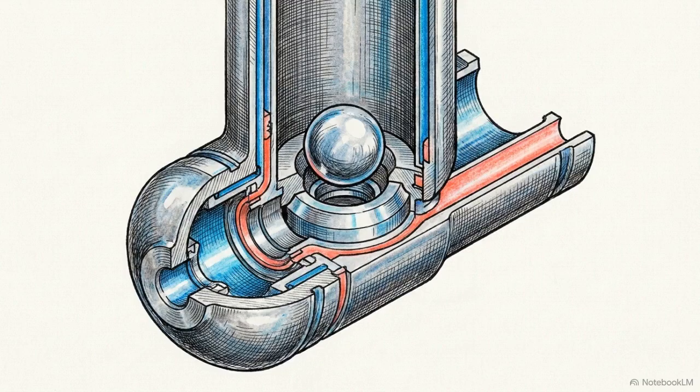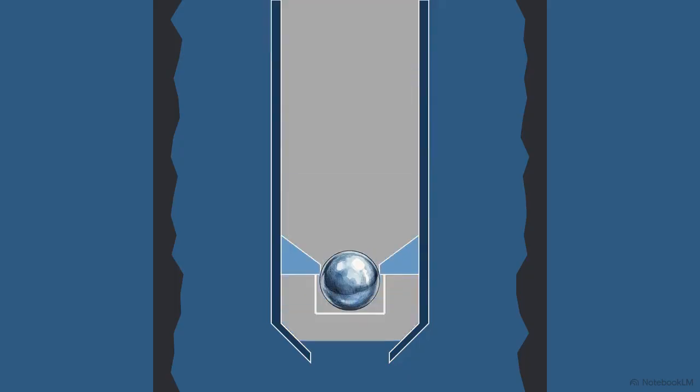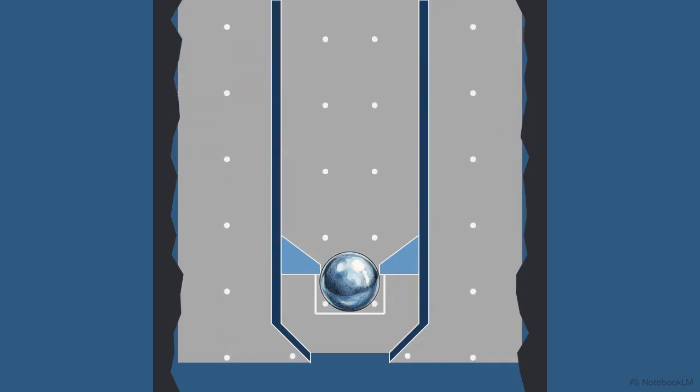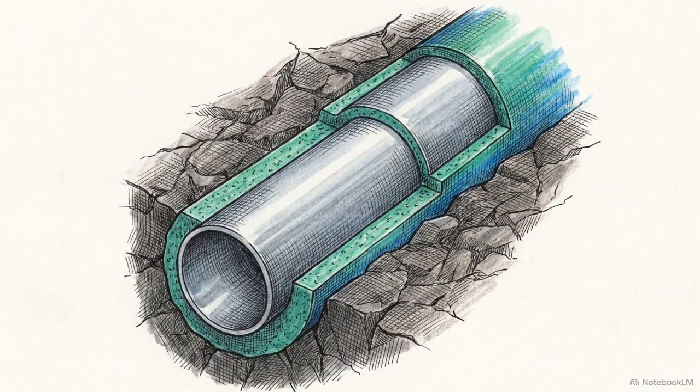At the very bottom of the casing string sits a float shoe. It contains a heavy ball and seat check valve. The high-pressure pumps force the cement down through the valve and up into the annulus. Once pumping stops, the heavy hydrostatic weight of the cement tries to flow backward, which slams the ball against its seat, locking the cement in place. The hardened cement and nested steel turn a temporary excavation into a permanent high-pressure industrial conduit.